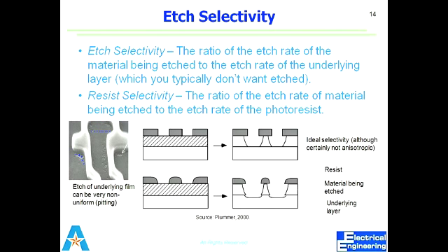But in that case, I always consider my substrate as the etch stop. It's very selective towards the etchant, so it should not etch away. In this case, the over-etching process cannot be done if you don't want to etch your substrate, because the etchant is not selective with respect to the photoresist, and is not selective with respect to the substrate. In polymer processes, if you know about polymers, that is always an over-etching process.